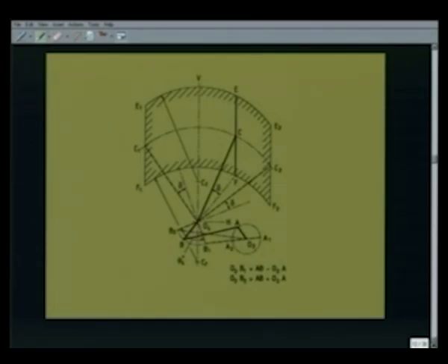To determine the wiping field, we see that because it is a parallelogram linkage, the point C goes in a circle with O4 as center and O4C as radius. Because it is a parallelogram linkage, all the points of the coupler move in identical curves.